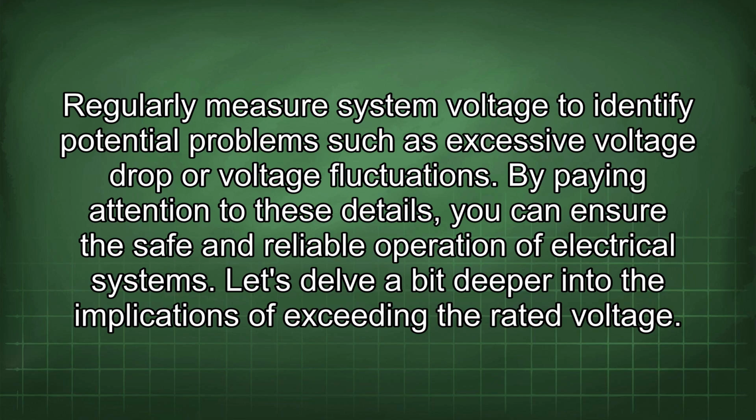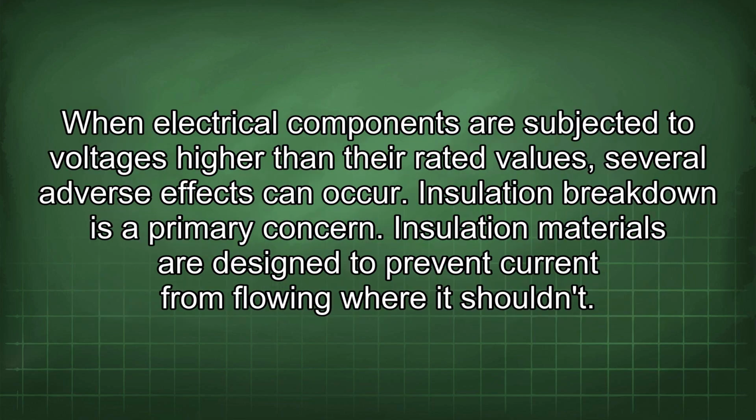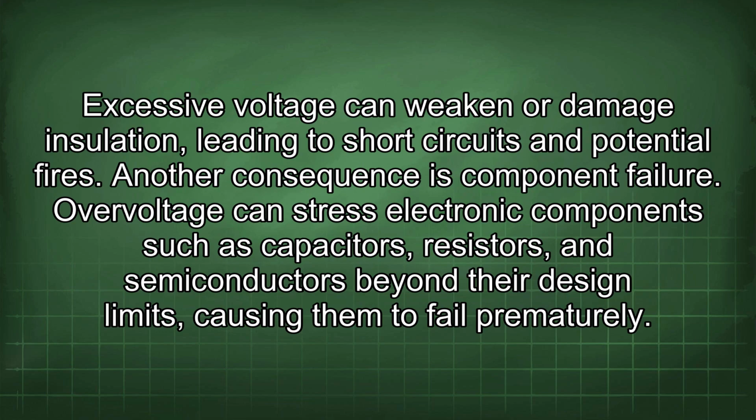Let's delve a bit deeper into the implications of exceeding the rated voltage. When electrical components are subjected to voltages higher than their rated values, several adverse effects can occur. Insulation breakdown is a primary concern. Insulation materials are designed to prevent current from flowing where it shouldn't. Excessive voltage can weaken or damage insulation, leading to short circuits and potential fires.